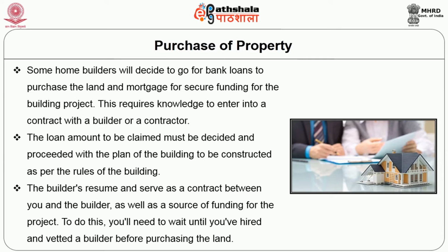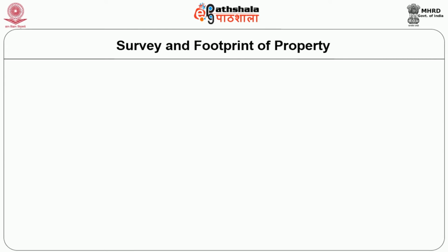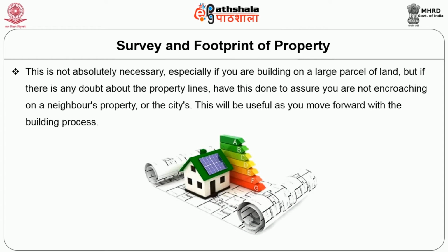After purchasing the land, have the property surveyed and the footprint of the house located. This is not absolutely necessary, especially if you are building on a large parcel of land. But if there is any doubt about the property lines, have this done to assure you are not encroaching on a neighbor's property or the city's. This will be useful as you move forward with the building process.